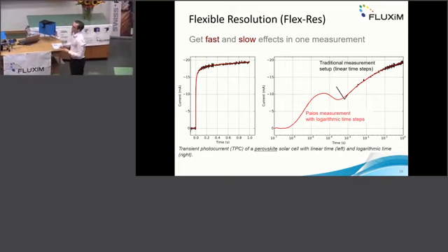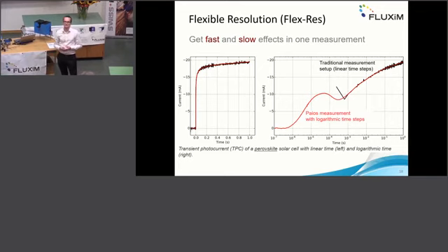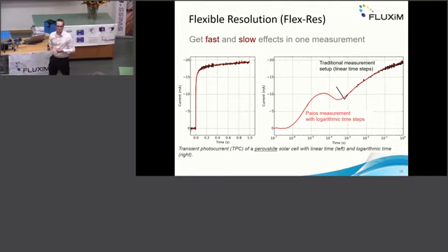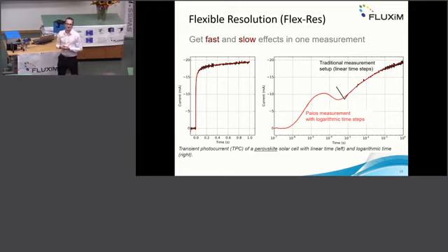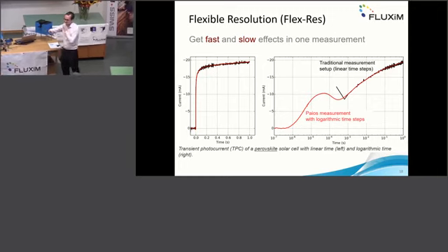So let's imagine you use a classical oscilloscope and you can maybe measure 10,000 points. What you see here is then when you just plot it linearly, you see there's not real difference. So you see just the black curve here. When you plot it in log, you see, of course, because of the linear time sampling, you miss all the interesting features that are faster than your time step. So what we do is we measure internally with up to 30 million time steps, and we then convert this to a logarithmic time grid, some time spacing.